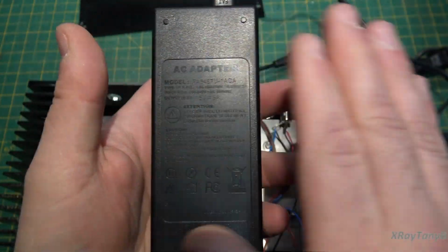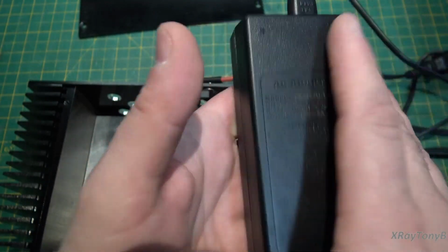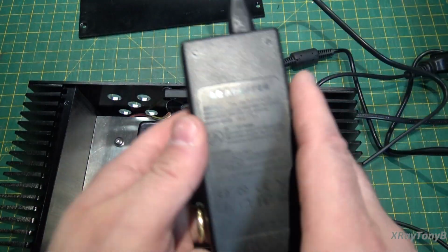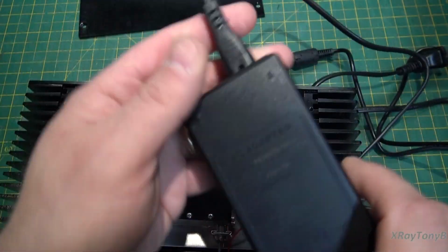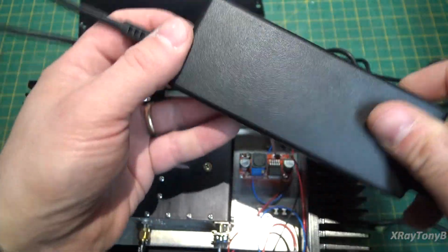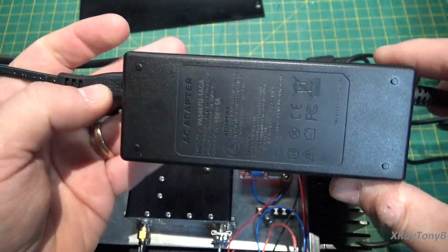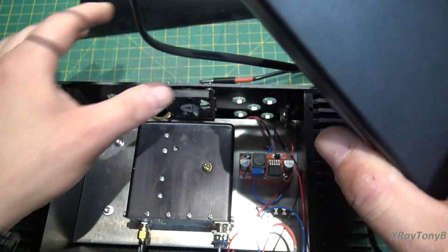And you have to watch, many laptops use 19 volts. You put one of those in here, you're going to damage it. So very important, make sure if you're going to use an old laptop supply or something that you get 15 volts. These can be purchased online, eBay type, Amazon type places, very, very inexpensively.